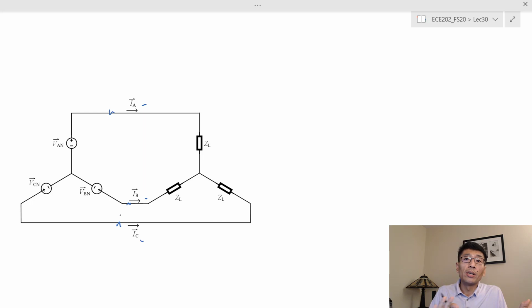You transfer power over a long distance, and this will save a lot of cost compared to using 3 single-phase circuits. Three single-phase circuits would require 6 wires, 1 go and 1 return for each phase, so 2 times 3 gives 6 wires. Now you only need 3 wires. This is one of the biggest advantages of the three-phase system.